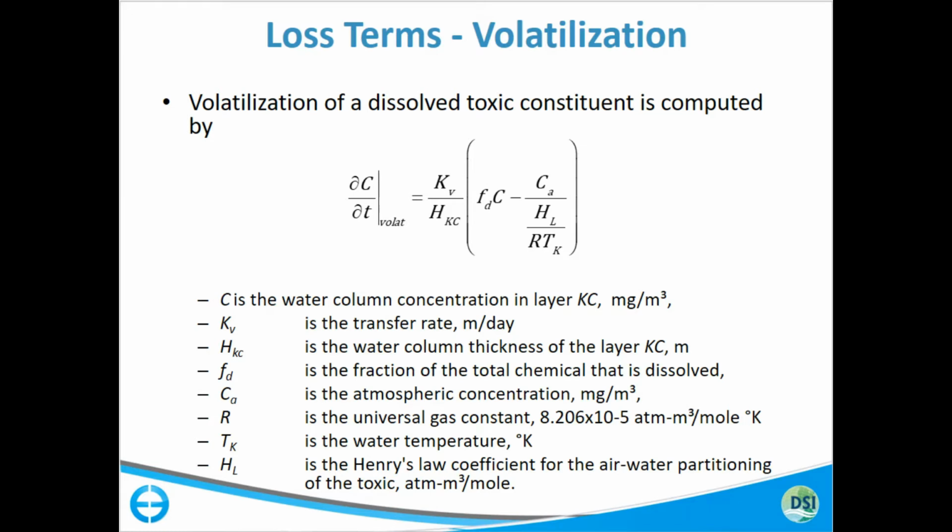Lastly, we added the volatilization term to EFDC. So your basic volatilization equation here, this is your net transfer rate, and then your depth, essentially your layer thickness of your top layer.